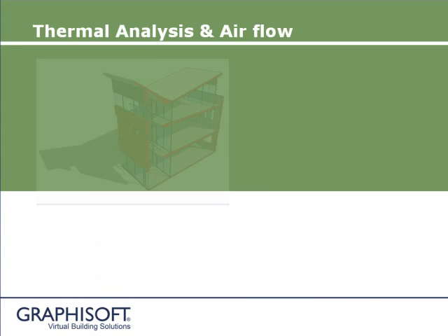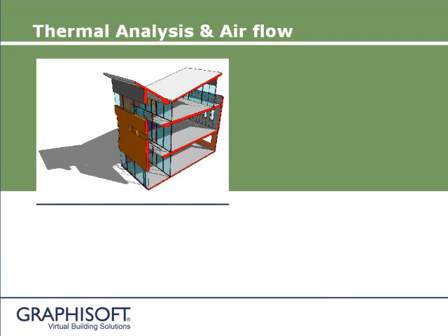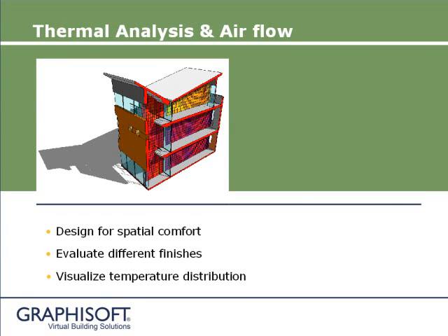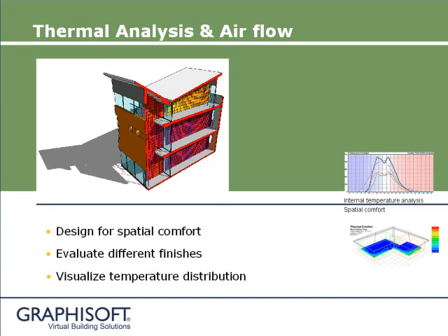It is easy to design for thermal comfort. Effortlessly switch building envelope materials and internal partitions, and get a visual presentation of the thermal conditions. For more detail, you can add material properties to all objects, produce an annual hourly operational schedule for occupancy, and add data about individual items of equipment. Internal hourly temperatures can be shown for any day of the year.